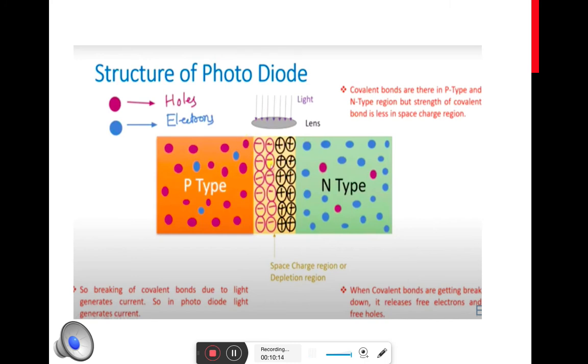That is how it came about: the majority carriers, electrons in the n-type material, leave the n-type material and leave behind a positive ion. When they break their bond and go to the other side, they leave behind a hole, denoted by the positive ion. Similarly, when the holes in the p-type flow to the n side, they leave behind an electron, and that is shown by the negative ion.